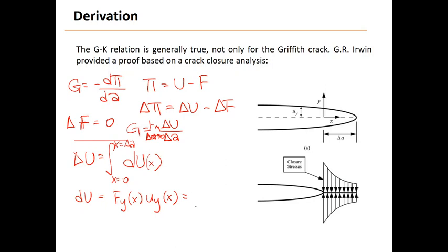So we just need to turn that into the corresponding stress, because we know this crack tip stress field, which is sigma yy, times uy, and we also know the displacement uy expression. Now we just need to go back and find these terms from the universal crack tip stress field and substitute the corresponding values, right? So let's do the displacement first.